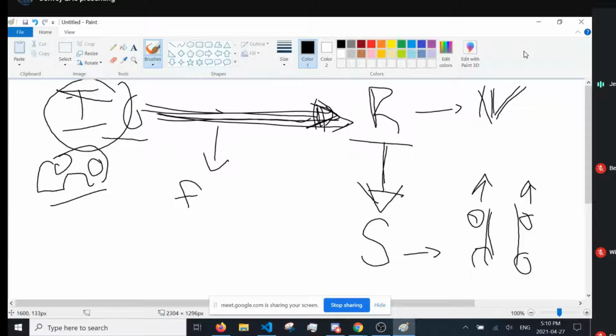You're not able to manipulate the variables that you might want to, right? So in this case, I can only manipulate voltage, and I can't actually manipulate directly the robot's wheel speed. So how do we solve this problem, right? And the reason for that is because, again, it's an open loop system. So any information that we're putting in is ultimately being funneled through from the robot inputs into this state, right? And there's nothing going around.